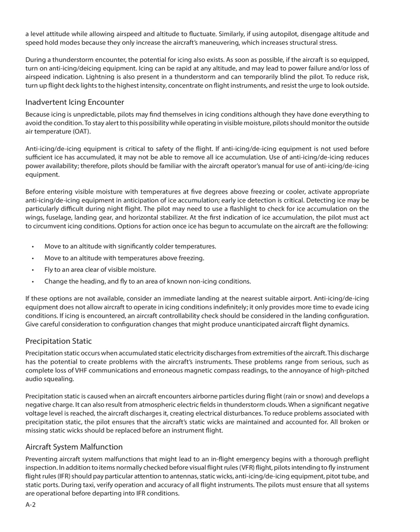Move to an altitude with significantly colder temperatures. Move to an altitude with temperatures above freezing. Fly to an area clear of visible moisture. Change the heading, and fly to an area of known non-icing conditions. If these options are not available, consider an immediate landing at the nearest suitable airport.